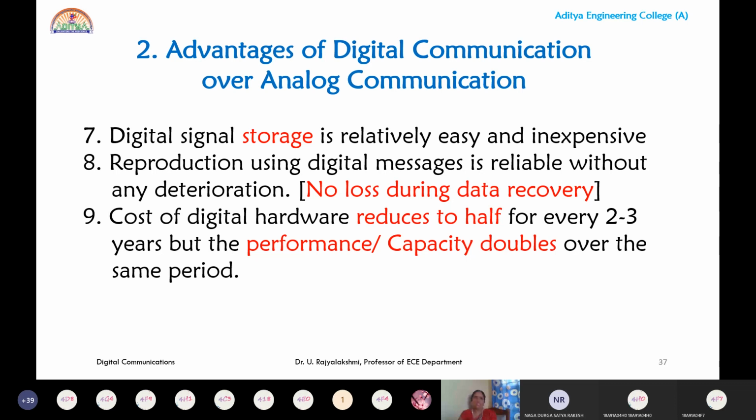So at the receiver, the recovery rate of the digital message is more compared to that of the analog message because of the presence of repeaters in the channel. Because we are using repeaters, every time the repeaters will regenerate the input encoded data. By regenerating, you can reduce the losses and you can generate the signal without any deterioration or loss. So data recovery is good in digital communication compared to analog communication. That is the 8th one.